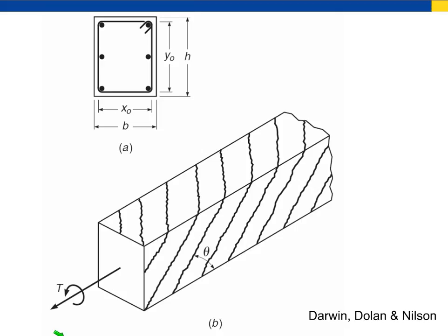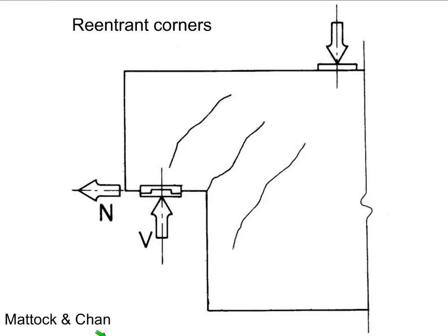Well, this was an industrial construction. They did not analyze it correctly, and what happened is they ended up getting twisting or torsion in the member, and they didn't design for it, so they didn't have adequate closed stirrups in the beam, and therefore the cracks just opened up and we saw them, and actually the strength was not adequate either, and there's quite a bit of retrofit work that had to be done here.